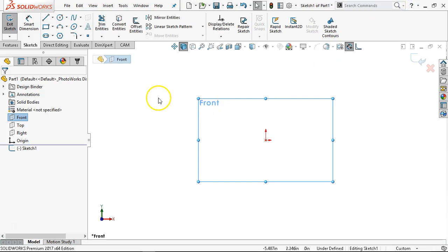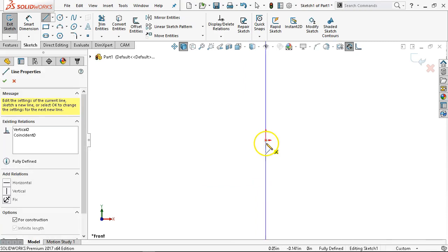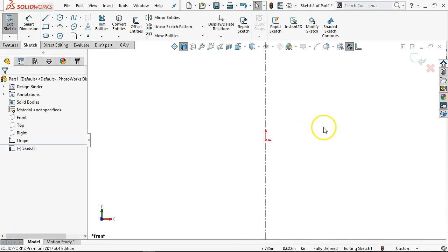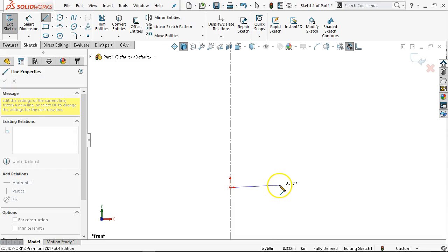The only reason that it's infinite length is that it is convenient to never run out of center line, or have one small enough that you might put an object line over top of it, that you would have to do that select other thing to find it. So vertical, infinite length, drop it on the origin. I think it's about as easy just to go ahead and select than it is to uncheck boxes and back out of the command once you've gone down the center line path.